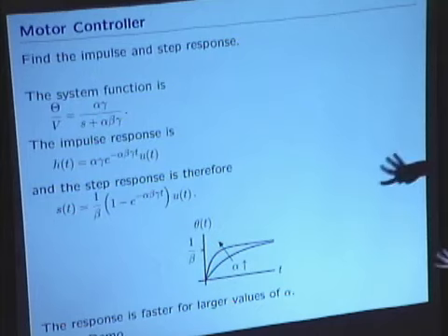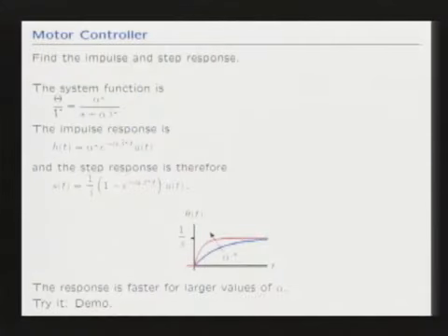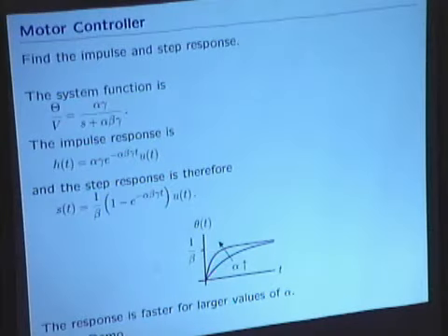Okay, just doing the same kind of analysis that we did for the op-amp, the step response goes from being the response of a pole, which is an integrator, to being this kind of a response, which has a final value. That converts it from being voltage to velocity into voltage to angle.